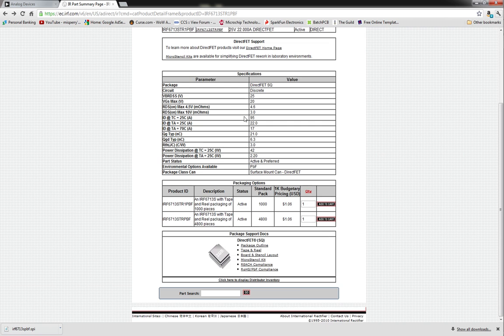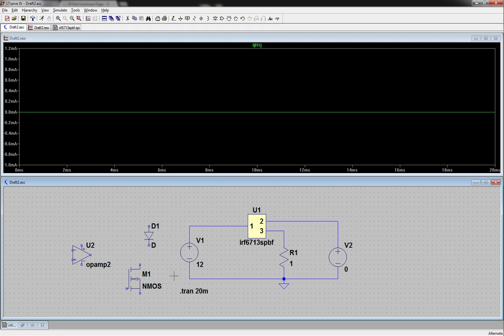Of course, they're not going to show it, but any other type of power, usually the power MOS type stuff, will have an internal diode where the anode is at the source and the cathode is at the drain, and it's just inherent to how they build it. It creates a diode barrier, creates a PN junction right there.